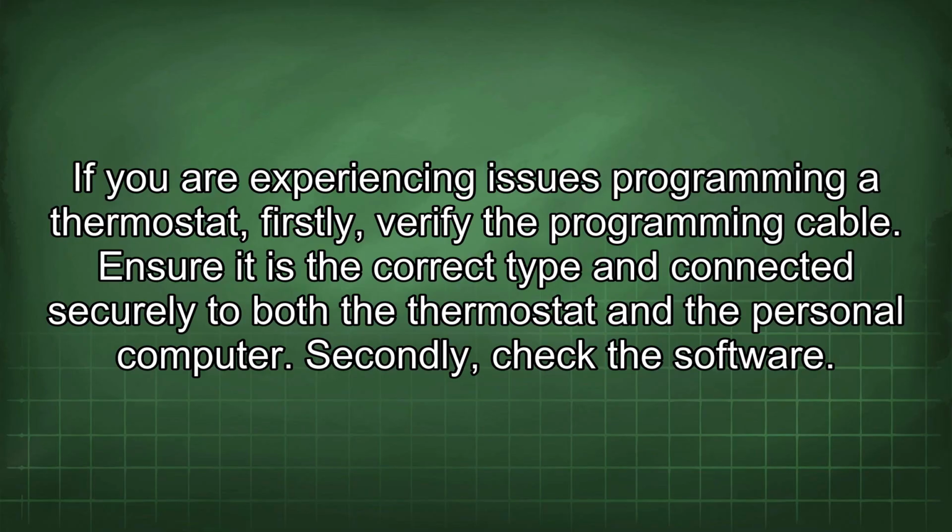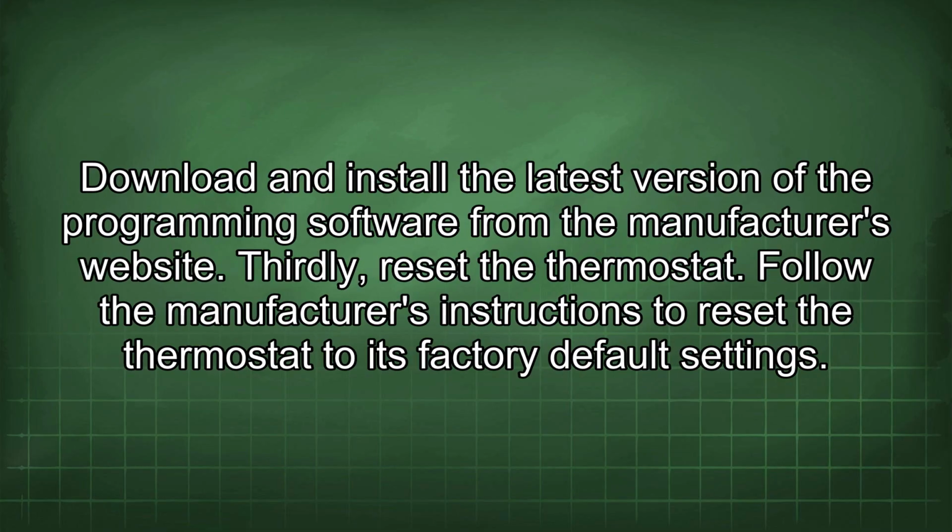If you are experiencing issues programming a thermostat, firstly verify the programming cable. Ensure it is the correct type and connected securely to both the thermostat and the personal computer. Secondly, check the software. Download and install the latest version of the programming software from the manufacturer's website.